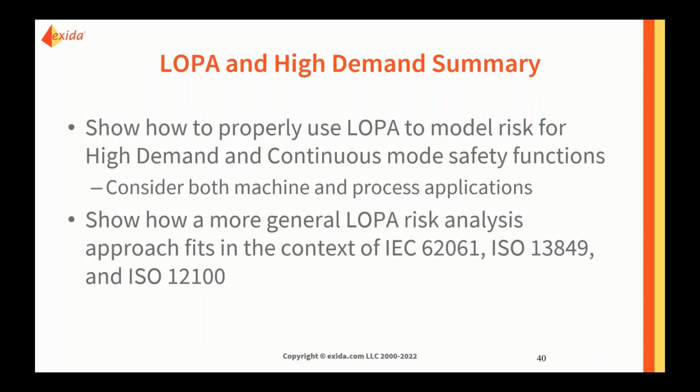So in summary, I hope we've presented the LOPA technique as an effective model for risk in both situations where we're considering a high demand and continuous mode safety function, as well as the standard low demand mode safety function that it's most commonly used for from the process industry. And also we've shown how the more generalized LOPA approach can fit on top of the 62061, 13849 simplified risk graph methods of risk analysis.